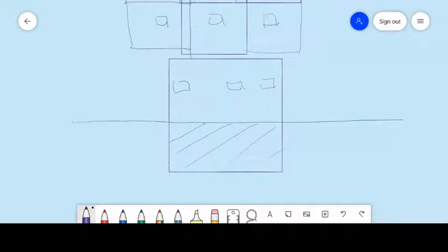Now, if the weight of the excavated soil is equal to the weight of the building, then that is the time that your foundation would be called buoyant raft or buoyant foundation or buoyancy raft. If you recall Archimedes' principle, then that's the reason behind why it is called buoyancy raft.